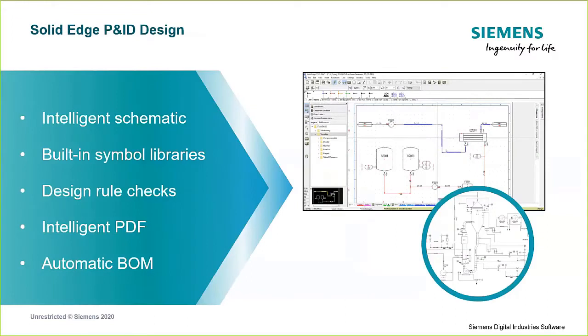First, the P&ID. It's a 2D intelligent schematic, and it details how things logically get connected together. It describes the process workflow, capturing the connectivity of the modules and the individual components. Now, we say intelligent to describe the schematics because it's working off a component database. And because of this, information for the pipelines and symbols is easy to find and access, which saves time and reduces errors for the user.